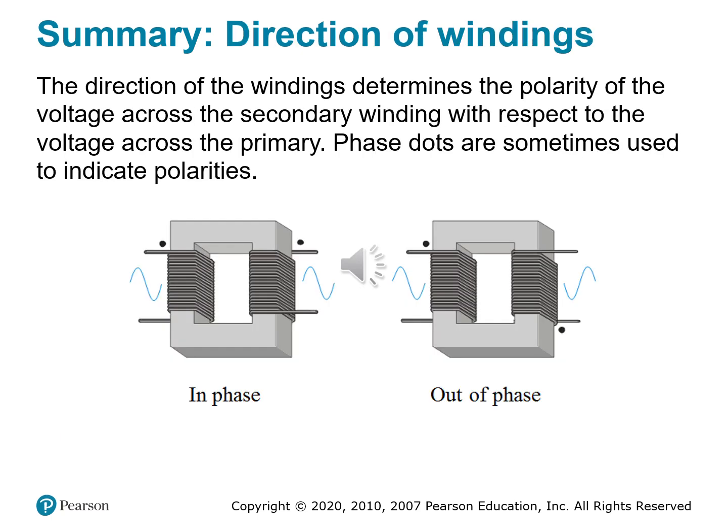All right, let's continue with the construction of one of these transformers, and let's look specifically at the winding direction, that hidden twist behind polarity. So far we've covered transformer cores, turns ratios, and coil interactions, but here's a twist, literally a twist. The direction of a coil's winding can affect the polarity of the voltage on the secondary side of a transformer. This matters because transformers don't just change voltage. They also determine the timing and direction of current flow between coils.